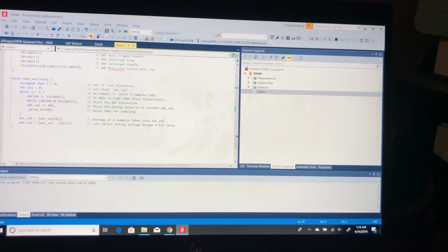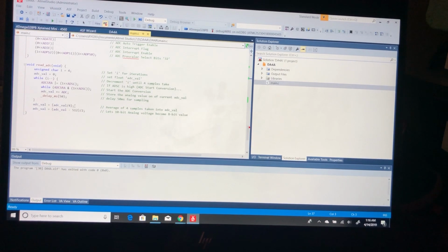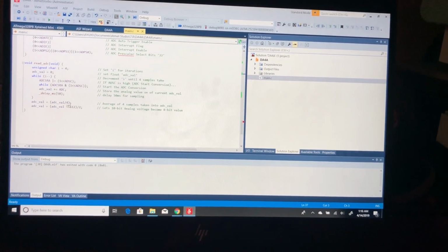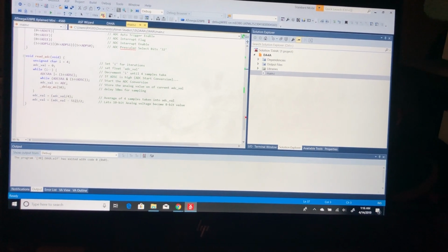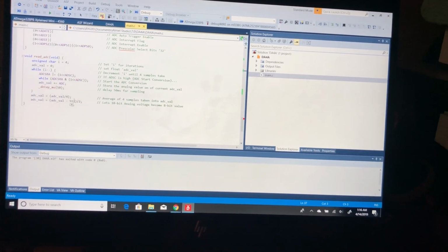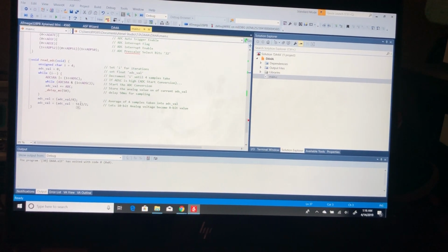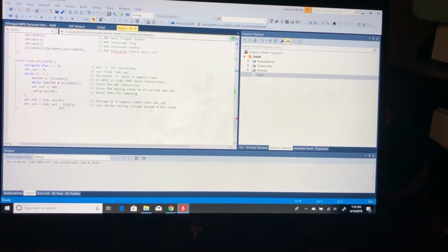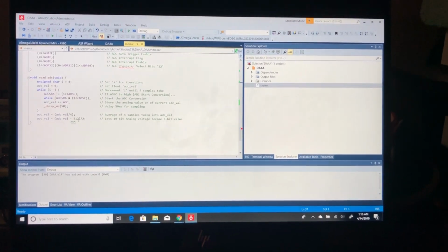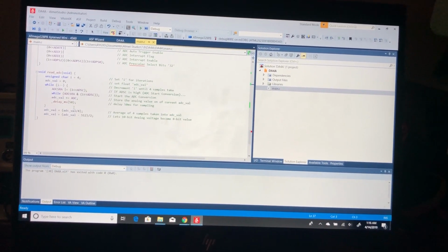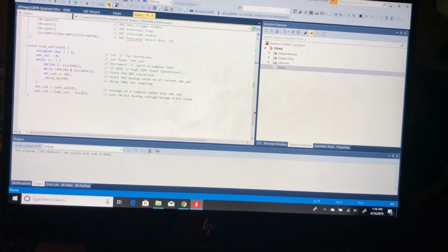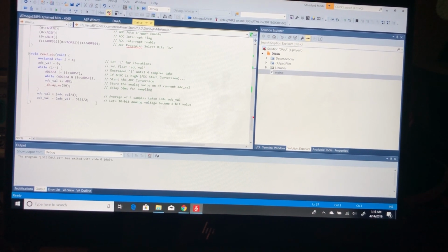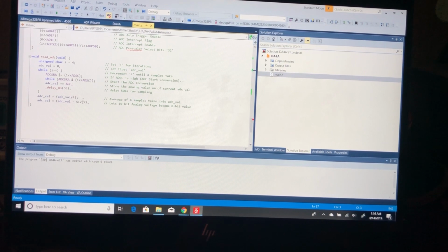The max value on the voltage divider happens to be 5 volts in this scenario, and the lowest happens to be 2.5 volts, because I used a 1K potentiometer, max at 1K and then 0 at the lowest. So I just subtract half of it, and then I divide it by 2 so that we get an 8-bit integer value, which is this last line.